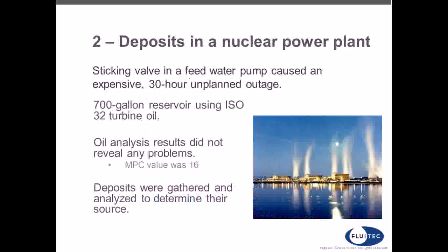And all of the major safety systems are tested on a regular basis. In this particular case, there's a feed water pump that had a valve, and they did a routine monthly test on it, and they stroked the valve. The first time they tried to stroke the valve, it stuck. They immediately did it again, and there was some vibration and some sticking, and finally it kind of freed itself and could move. Then they tested it a third time, and it moved without a problem.